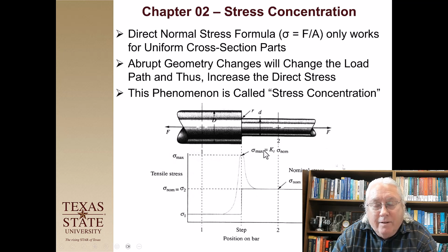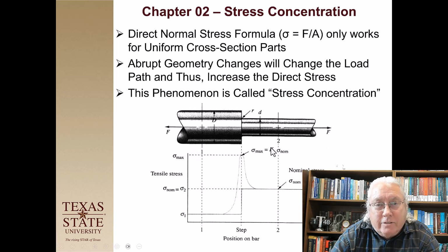And so for this case here, depending on this little r value, this K factor is going to change. An important thing to remember about stress concentration factors is that the K factor is only a function of geometry. It has nothing to do with the forces or the type of material. It only has to do with the geometry. And we'll see that when we look at these charts that let us compute the K factor. You'll see the only thing that matters is the geometry.